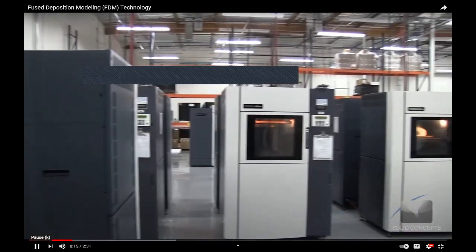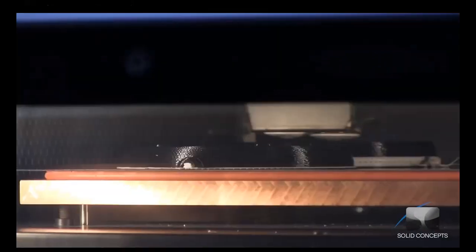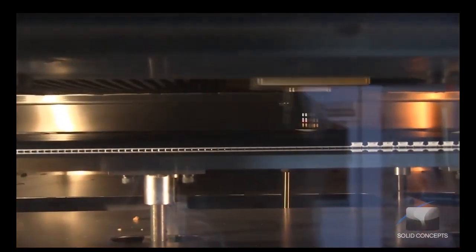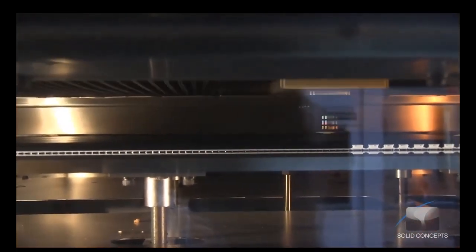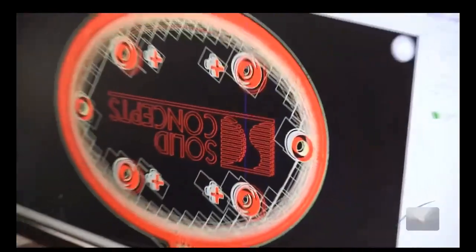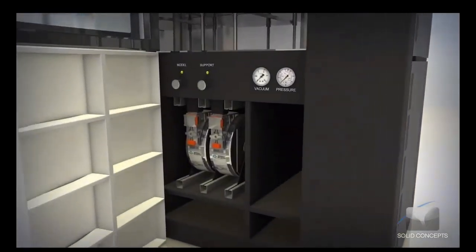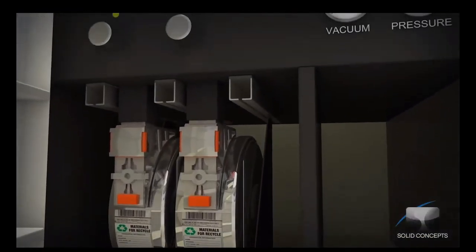Fused deposition modeling, or FDM, is a layered additive manufacturing process that uses production-grade thermoplastic materials to produce both prototype and end-use parts. This technology is known to accurately produce feature details and has an excellent strength-to-weight ratio. FDM is ideal for concept models, functional prototypes, manufacturing aids, and low-volume end-use parts. The FDM process begins by slicing 3D CAD data into layers. The data is then transferred to a machine, which constructs the part layer by layer upon a build platform.